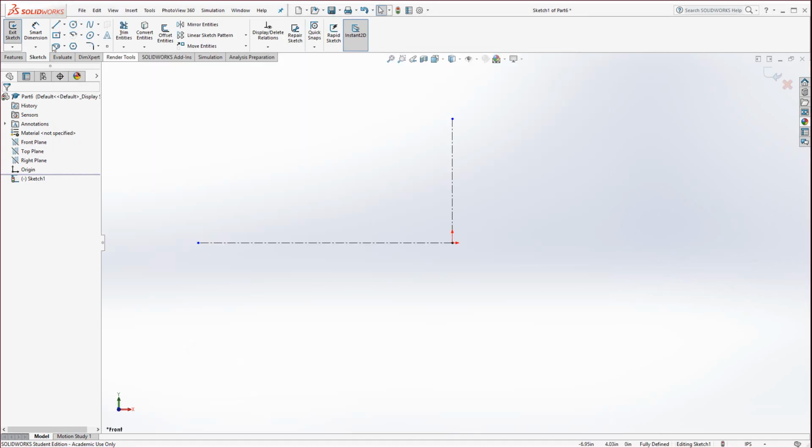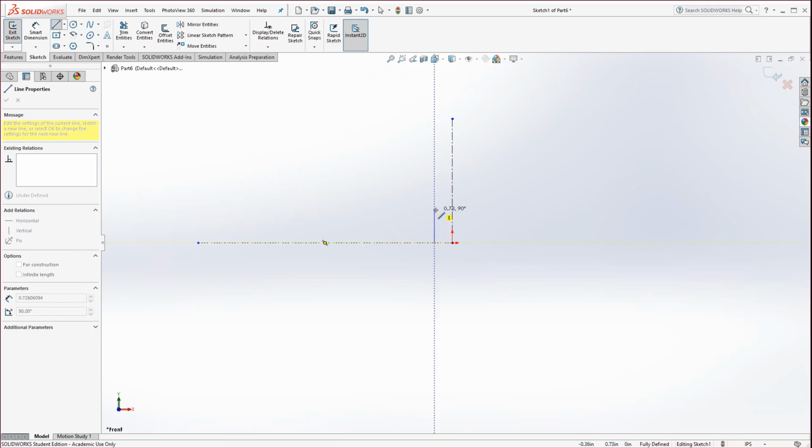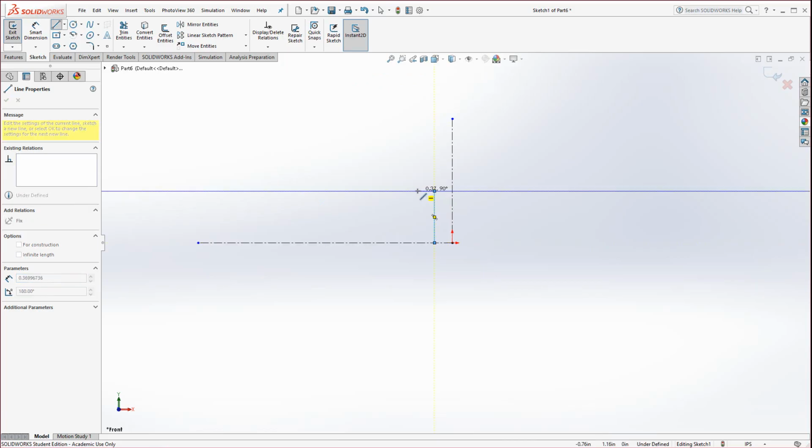And so let's begin. Find the line tool, glide up just short of the vertical center line, so I'm just a little to the left. I'm going to click and drag up a line about 1 inch in length. Make sure it's vertical. Click again. Drag across, make sure it's horizontal.